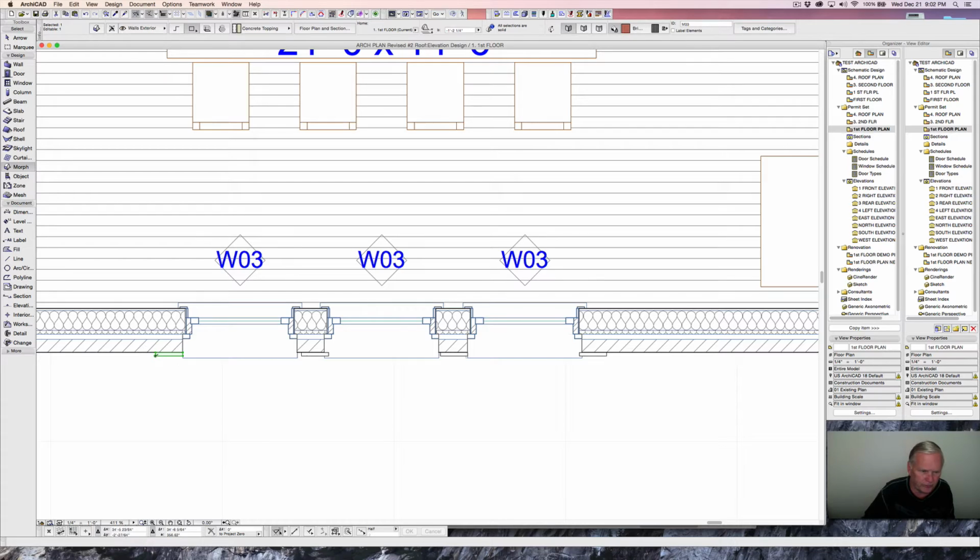You have to be careful. You don't want to just click on an edge of a morph because you start pulling it. You're pulling it just from that one corner. So important to do the Control D, and that way you move the entire morph.